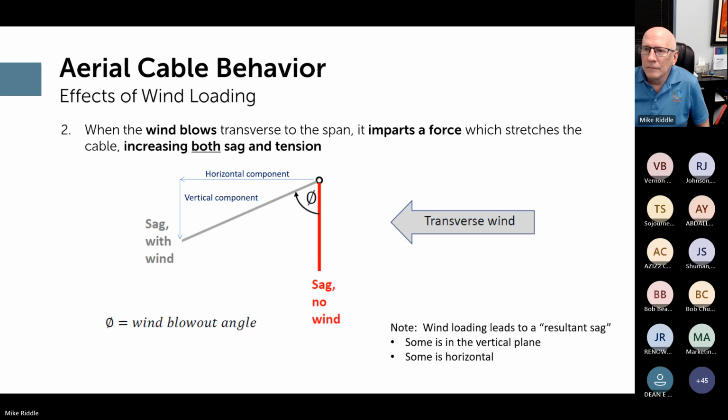Conversely, with dynamometer installation techniques, part of my comment has to do with the scale on a mechanical dynamometer. It's very difficult to interpolate between the markings on the dynamometer. So you're not going to get 3 or 4 significant places of tension measurement out of looking at a mechanical dynamometer. And for the digital dynamometers, that's a function of where the dynamometer is. Is it in series with the dead end?